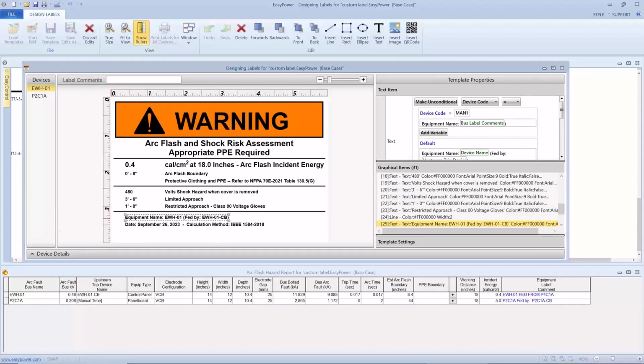Yeah, so Mike's saying, should we check the overcurrent protective device coordination to see what the upstream device should protect the panel? The answer is yes. So this is all done after I've completed my coordination and equipment duty tests.